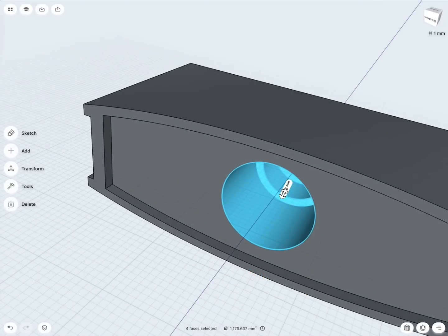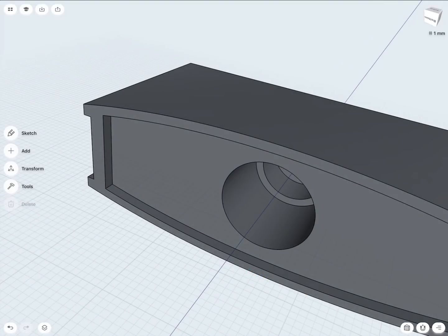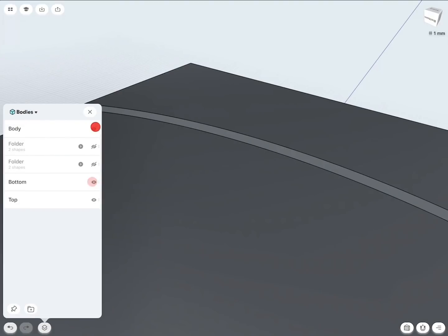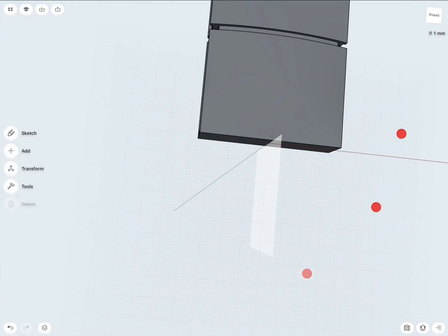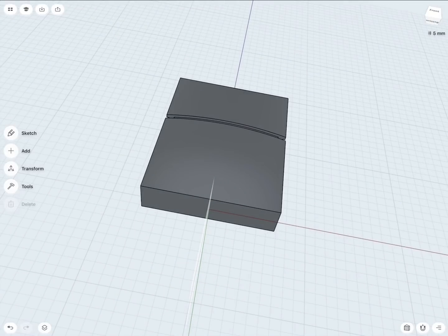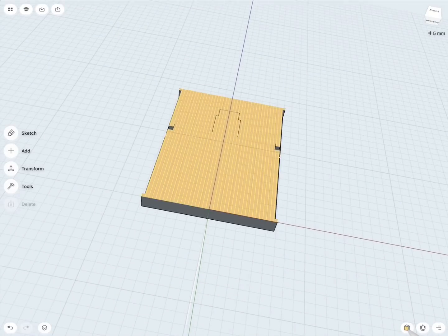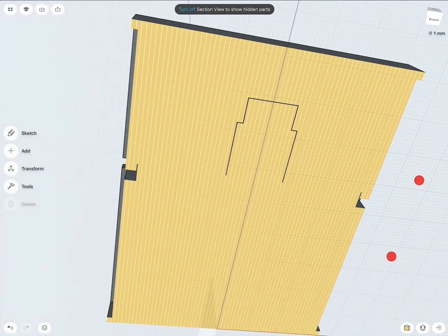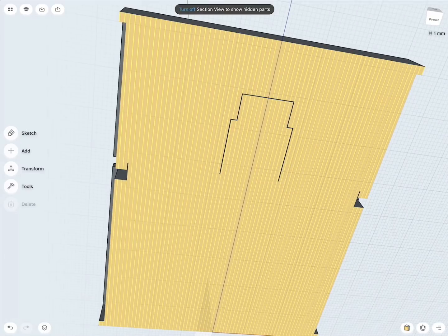Pretty good. Okay, so let's do a section look. Does everything we're doing right now line up? Are there any interferences? So the section view is actually very simple. We go to the grid we currently work on, and in the lower right corner, we click on that icon with the cube and the dashed lines, and there we are. Okay, now we have our nice distances.